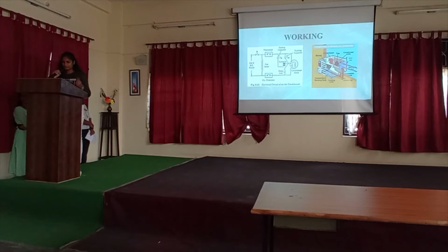The capacitor rating is given in volts, whereas its capacitance is in microfarads. It remains in the circuit for a short time until the motor starts. The third component is the running capacitor, besides the starting capacitor. The running capacitor has small capacitance but is heavy duty and oil filled. It remains in the circuit continuously and improves the starting torque and power factor.